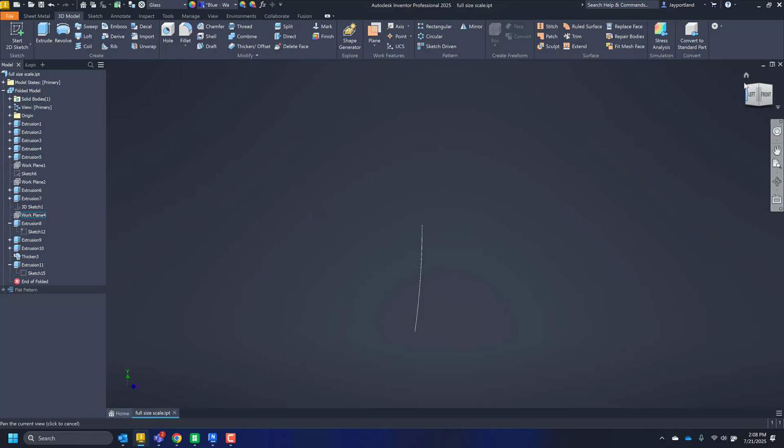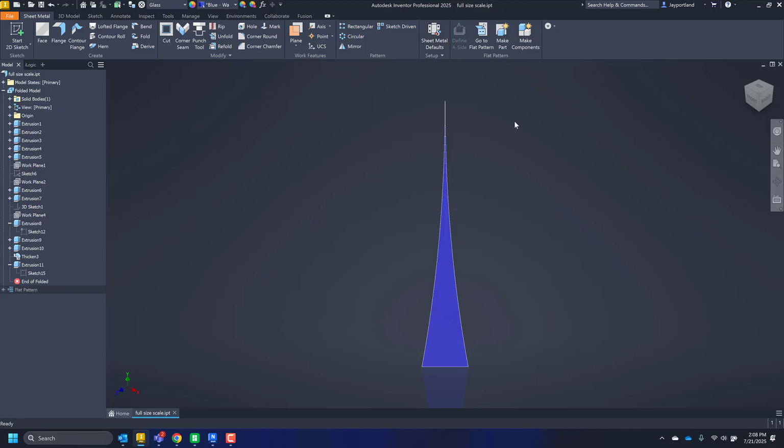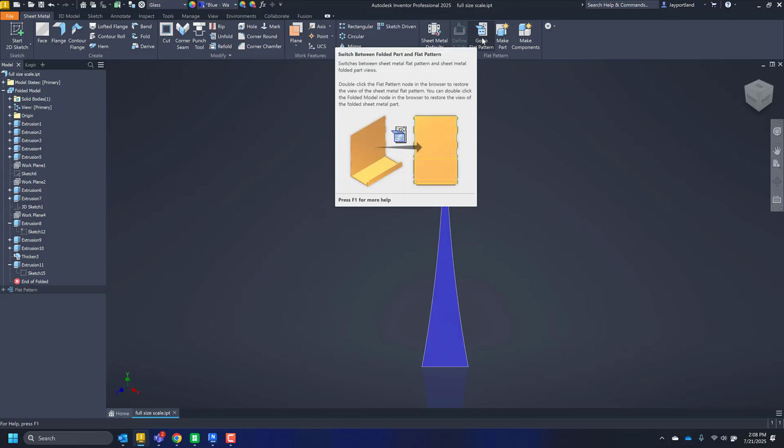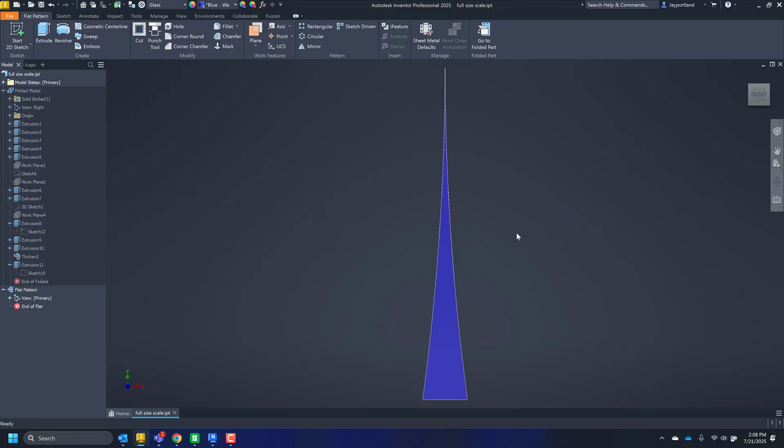And so that's how I wound up with this shape, Charlie. Got the shape. Now this is one solid. So after all these extrusions, I wound up with just that one little face. And then what I did, of course, when you go to the sheet metal, if you have a solid, you can convert it to a sheet metal. And then finally, when you have a sheet metal, you can go to create the flat pattern, or just make that flat pattern.